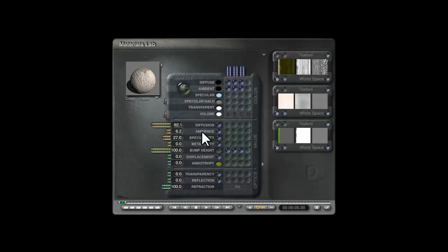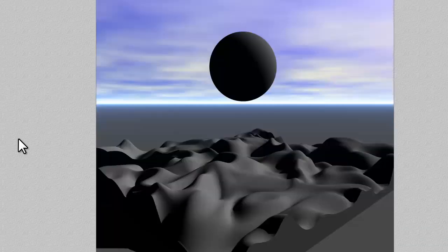In this case we've got an ambient intensity of 6.2, which isn't very strong, and the ambient colour is provided as the same as the diffuse colour. So if I boost this now so you can see the influence of this more, you'll see this material seems to have lit up. So I'm going to provide a balance between ambient and diffuse just to demonstrate this effect. So I'm going to check out of here now and we'll have a look at how things look.